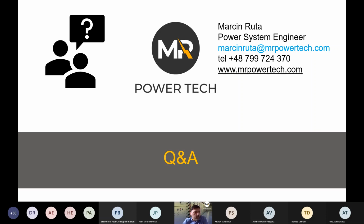If the calculated incident energy exceeds 40 calories per square centimeter in many locations, how would you fix this? As we all know, arc flash is all about time. So usually it's very easy to fix, but it depends very much on your local situation. If I have something which is above 40 calories, it usually means there is a long time. The long time is coming from something. It might be from protection, it might be from assumptions made in the study, I don't know.